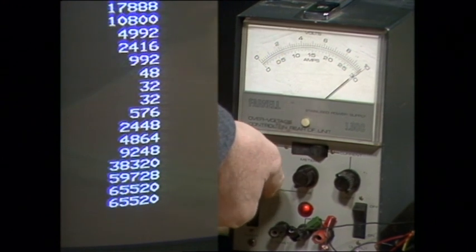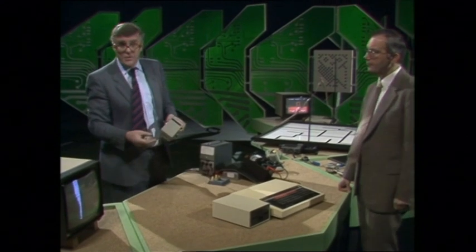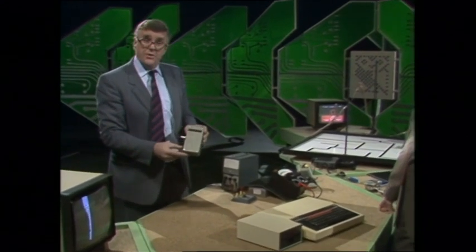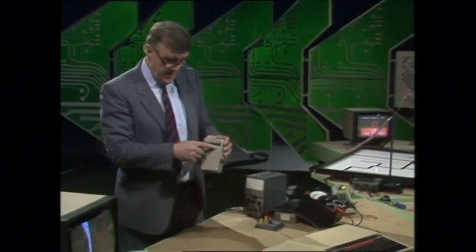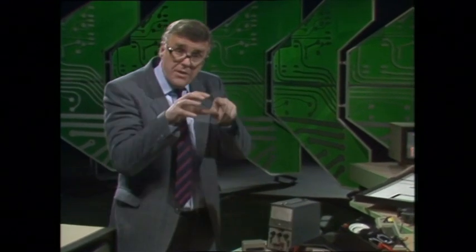And if we wanted that instead to display a voltage or a temperature on the screen, we'd have to have, so to speak, a fiddle factor in the program. We'd have to multiply or divide that number to rescale it to the correct scale. Well, what we have here effectively is an analog to digital converter. In a real situation, the digital information is fed into the computer itself. The computer can then make decisions and send back information to keep in control.